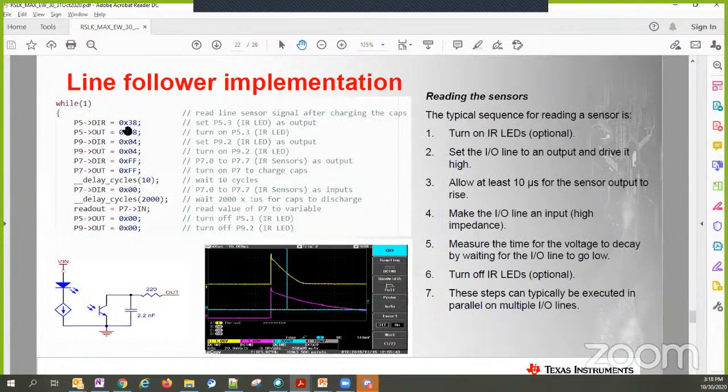So what is happening? If we look at the code, here you can see the while loop contains the number 1. While(1) means this code will be executed endlessly and never stop, because it executes as long as the statement in the brackets is true, and it will always be true because we have put in 1 manually.